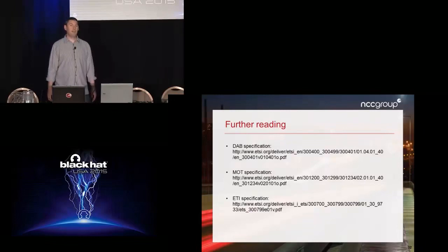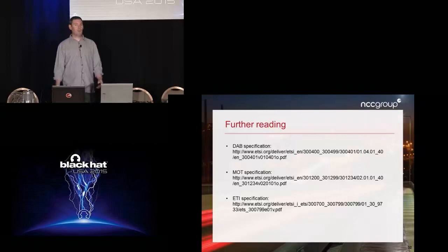To root cause the bugs, we use conventional hardware reverse engineering processes. We look for JTAG interfaces, we look for UARTs, anything that might provide us with debug information about what's going on with the crashes. But it's a case-by-case basis depending on the OS and the infotainment system in question.